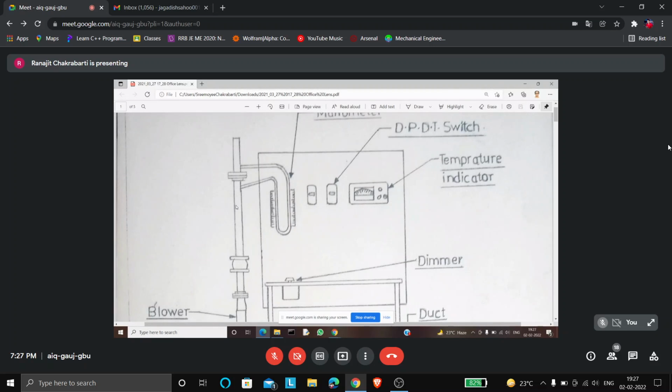and it goes through this pipeline. This is a pipeline, and we have a valve here for starting and stopping the airflow. And we have two flanges here, and here we have a plate. Centrally, it has a hole. That plate we call an orifice plate, which has an orifice hole. That orifice is meant for providing some resistance in the path of air.